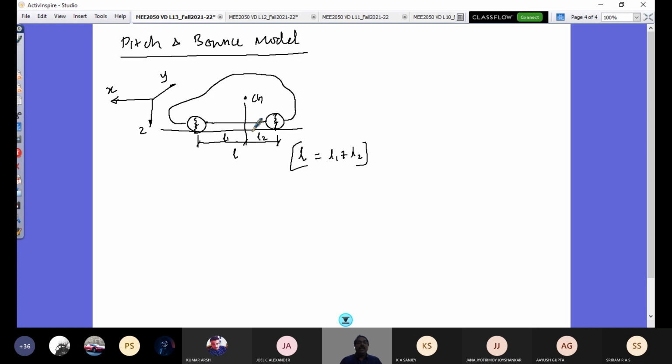Here this vehicle body is seated on this spring. So I have these two springs. I don't model an unsprung mass now. I will not consider an unsprung mass. The reason is the wide separation of natural frequencies of the sprung and unsprung mass, which makes the vibration of your vehicle body independent, and the unsprung mass independent in its natural modes. So the sprung mass natural frequency is not going to excite the unsprung mass, or vice versa. So I can make these two vibrations independent, and I would neglect the unsprung mass in my model.